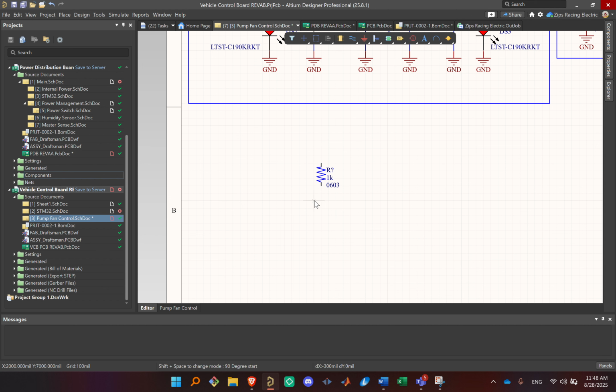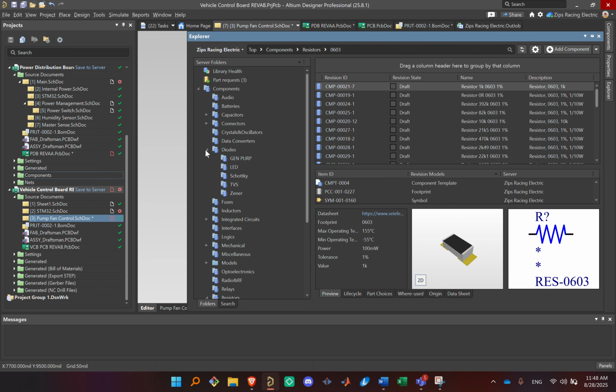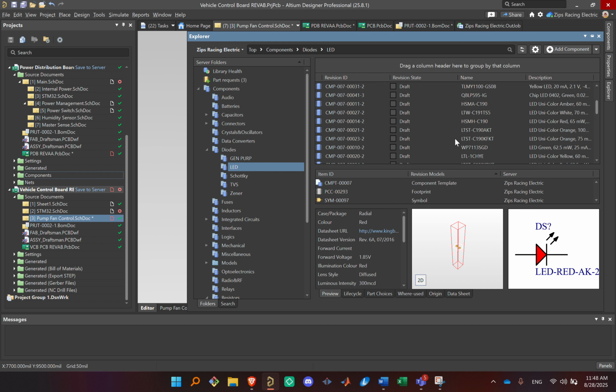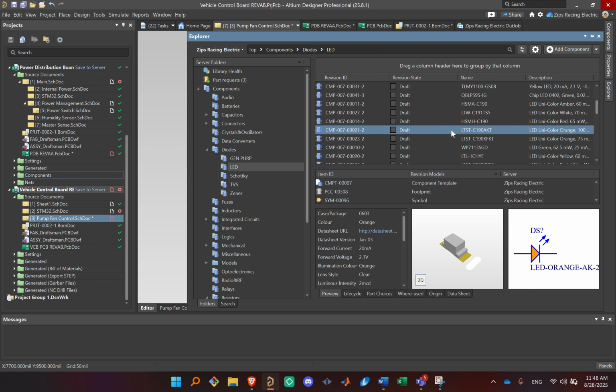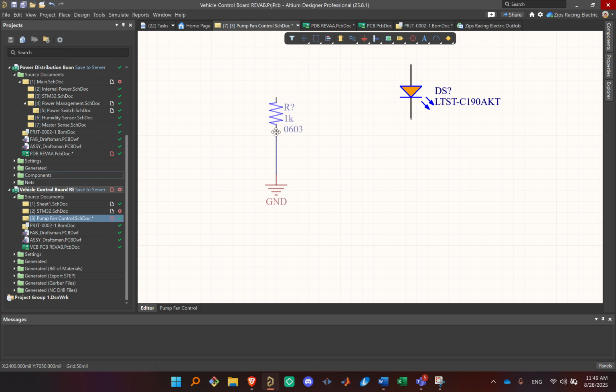Then we can add a wire by pressing Control W. And let's say we want to ground it. We'll press that ground and do that. Then let's say we want to place, I don't know, let's find something here. Let's place a diode. Let's place this LED. We're going to right click and place, and that'll come up in this menu, placed. Another thing to note is whenever you do that, it'll pull up another one. You just hit escape, so you're not having to add more diodes.